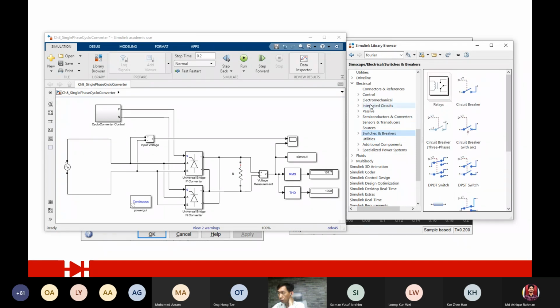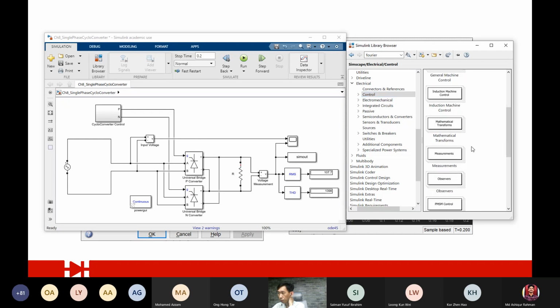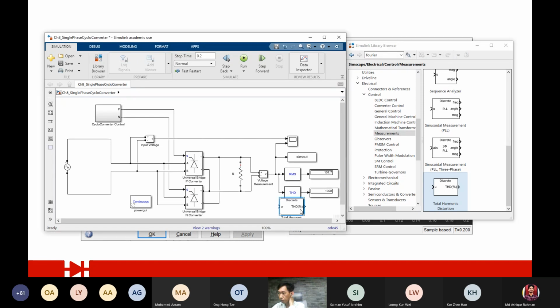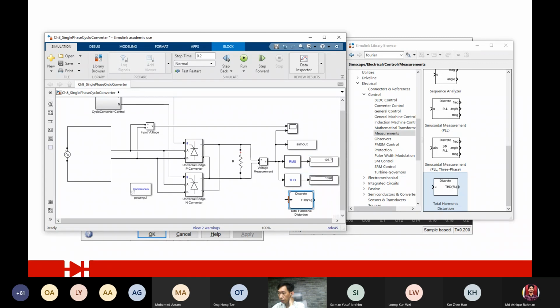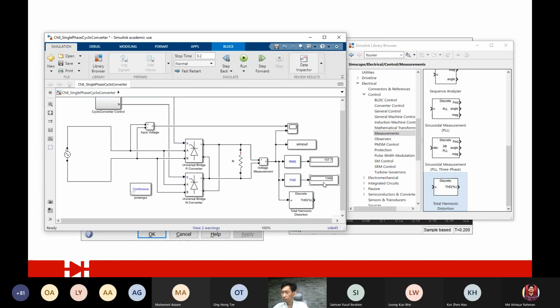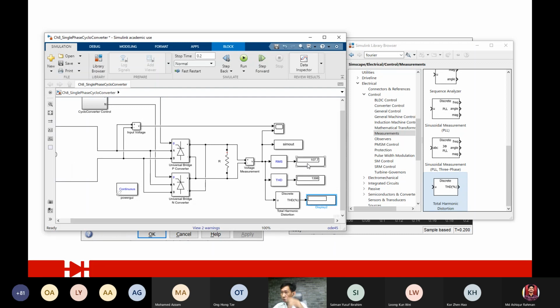Utilities, no. Breaker, no. Yes, see, there is another one here. This one will give you the percentage straight away. And of course, for THD measurement, if I'm not mistaken, this one measures just one cycle, so it will give you a different THD, because if you measure 2 cycles or 3 cycles, it will give you roughly a bit of difference. Also remember, because I also used it to control the voltage, I already chopped off the waveform, so you can see the THD go up 10 times.